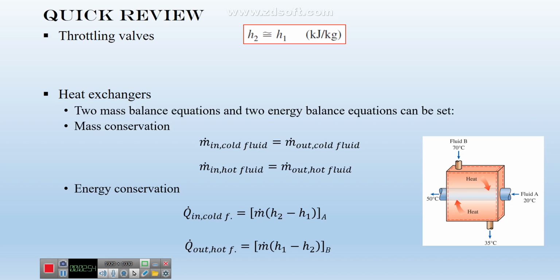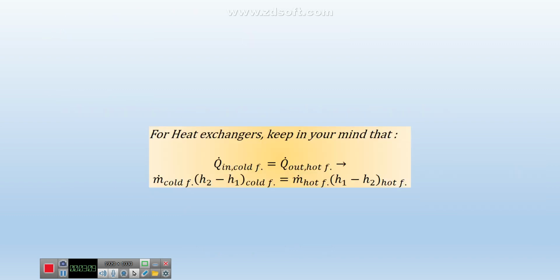Also, you can set two energy conservation equations for the hot and cold fluid. In the previous lecture, we proved that you can set this equation for the cold fluid and then this equation for the hot fluid. And eventually, keep in your mind that this is a fundamental equation in design of each and every heat exchanger. You can write Q in for the cold fluid equals the Q out of hot fluid, or this equation.